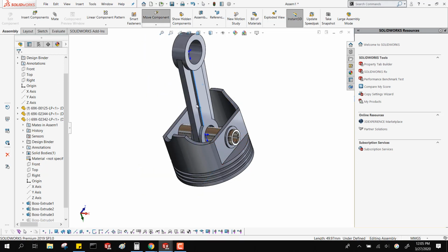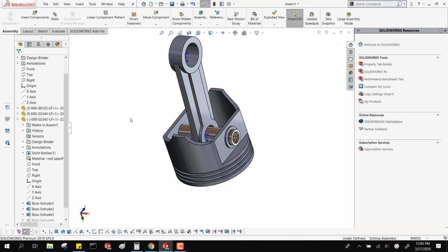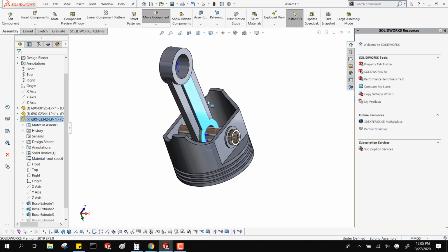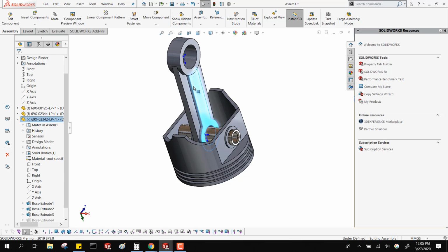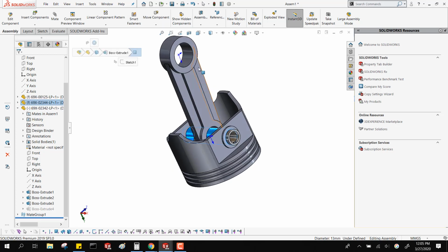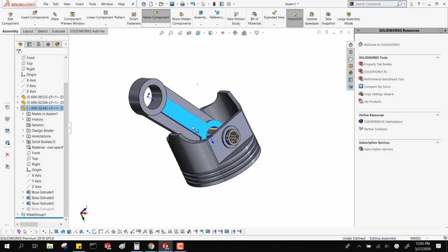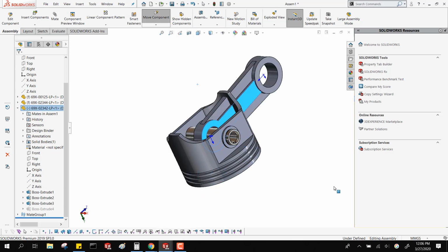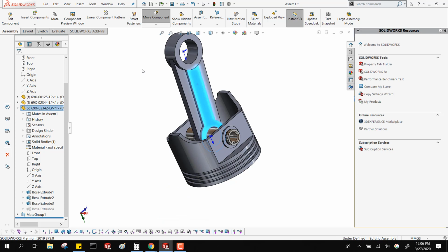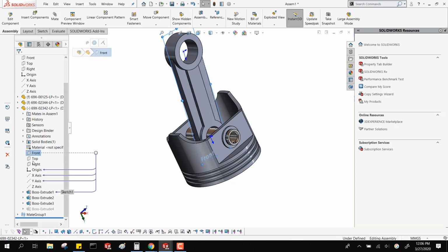I used to have 6 degrees of freedom where I could move axially along every axis and I could rotate about every axis. As I put the mates down, the coincident mate locked down the rotation in 2 ways. The concentric mate with the coincident mate has locked it down, so all I can do at this point is rotate about the X. But that is actually what I'm after. If I wanted to fully define this, I certainly can. I'll just put a quick mate on here.